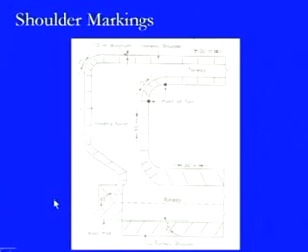This is one diagram which tries to show that this is a runway strip. With respect to this runway strip, on the two edges the markings have been provided at an angle of 45 degrees and they are located at a distance of 30 meters, but when it comes towards this turning area, then it will be located at a distance of 15 meters.